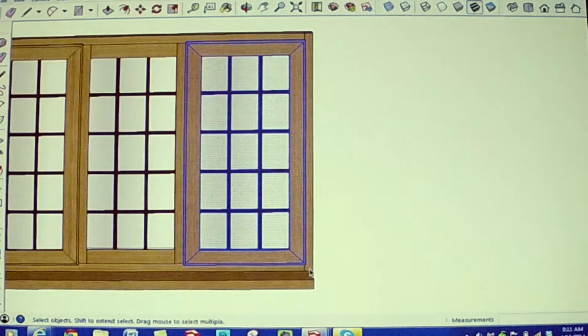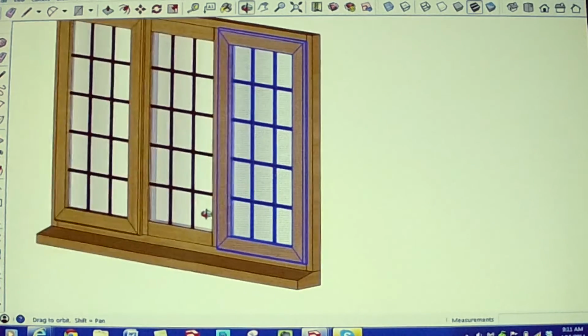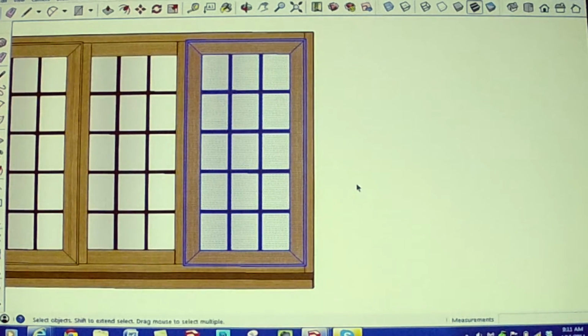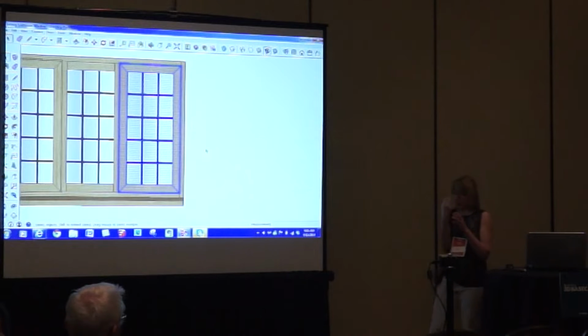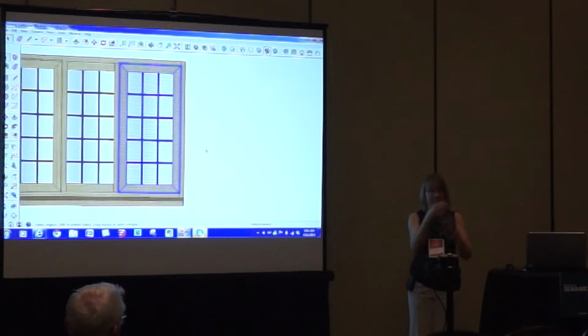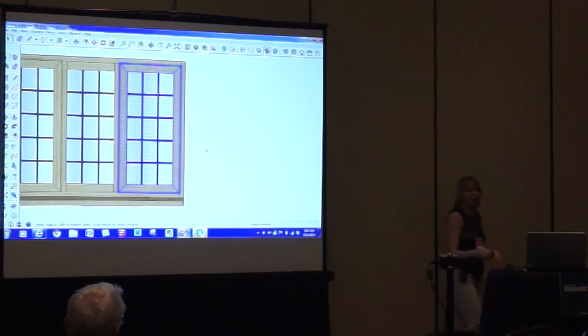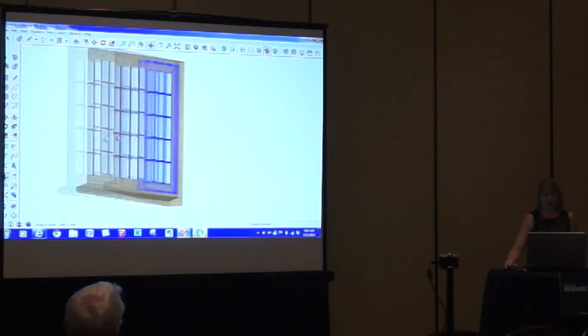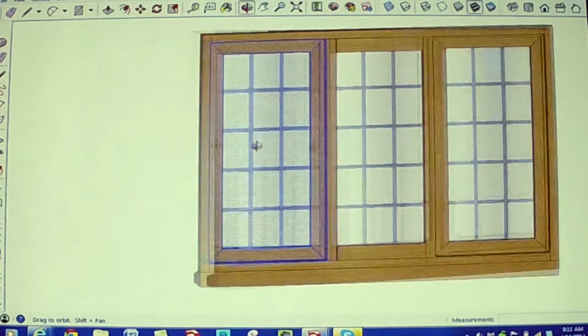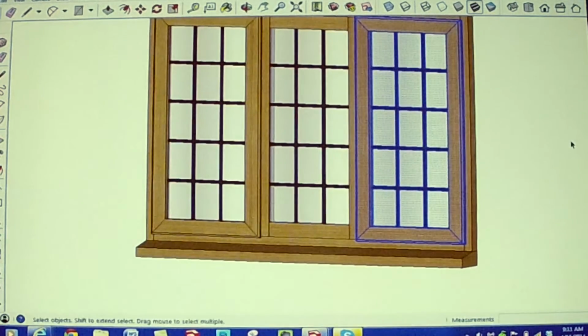selection box. Again, it looks like everything's selected that I want. So remember when you're selecting that not only what you see that's lit up is what's selected, but anything that's back in space into eternity behind it is also selected, even if you don't see it in this window. So it's a good idea to rotate around and make sure you look at the back of your model, that there's not a wall or something else back there that suddenly becomes part of your selection and disappears, and half an hour down the road you're like, what happened to my wall?